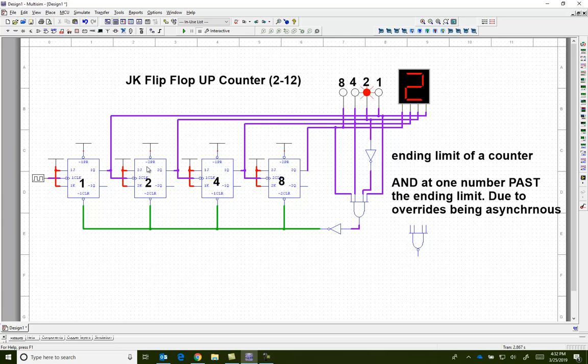I want to force it to be a 1 on. Now, remember the function of the flip-flop? You don't clear it anymore. Okay? What you do is you would preset it. So by doing this, what I am accomplishing is that whenever the AND gate gets a 1 here, it says, nah, don't show a 13. Override the 13, make the 8 a clear, so 0. Make the 4 a clear, 0. Make the 2 a preset, which is a 1 at the output. And make the 1's place a clear.